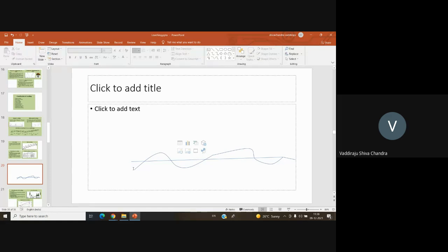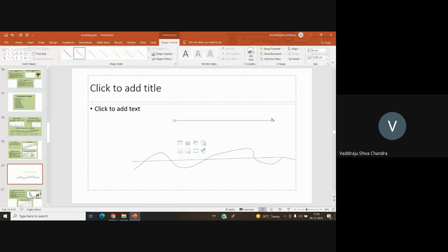So what we'll be doing is, we'll consider this as the center line. Okay, and at every 5 meters or 10 meters or 20 meters, depending on the interval which you want, you will be taking the staff readings. So like this. Assume that this is a 10-meter interval.